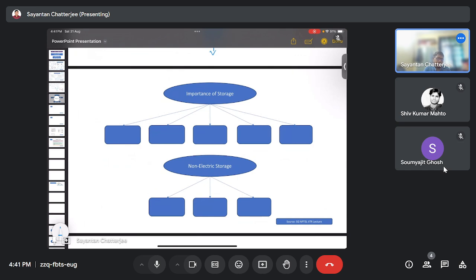So our aim is to make the power consumption profile flat. If we can make the power consumption profile flat, then the system requires fewer systems to be switched on or off, which we can control. So what we can do is calculate the amount of storage required to supply the energy which lies in between these two peaks.